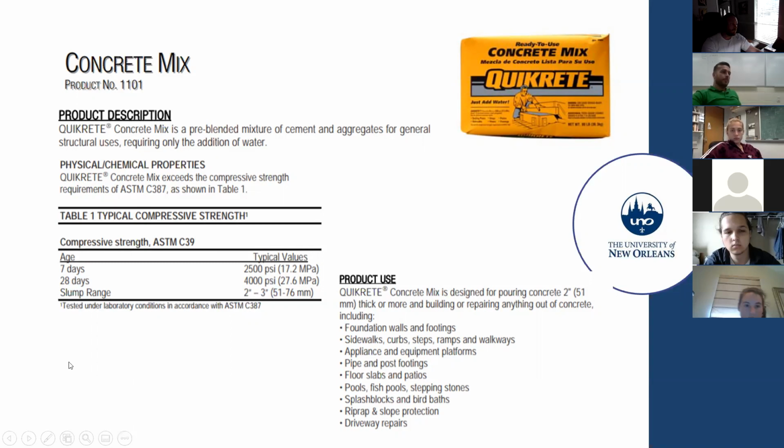So I keep watering and I keep the hydration going throughout the curing time. But it's not perfect. You have to have your curing room ready if you are shooting for these values. But we will see if it's 2,500 at 7 days or 4,000 PSI at 28 days. This is our goal. See how these conditions are affecting the strength of your concrete.